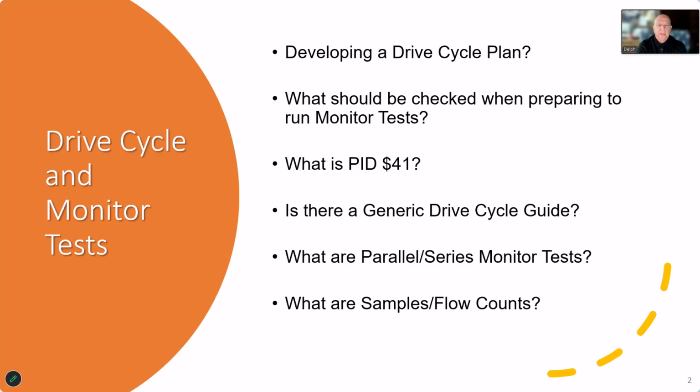What a PID 41 is, you may have seen it on your scan tool, and that's where when you go in to look at monitors, readiness monitors, and you see since last cleared, since 2008, there's been a second option called monitors this drive cycle. This is a hidden gem. When it works, and it's not that the system, the way it was designed, works well, it's how it's handled within the scan tool. I'm going to show you some examples of that because that can be a time saver for you too, especially if you don't want to clear existing readiness and maybe you've had a DTC and you want to drive it out. This is the way to do it.